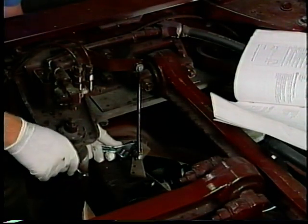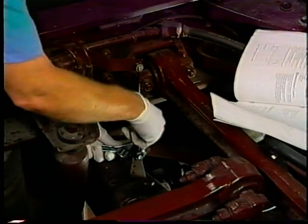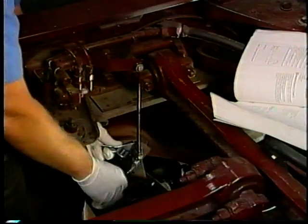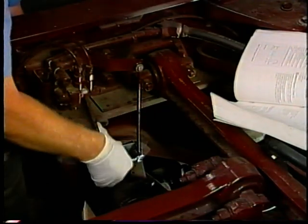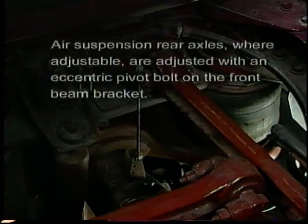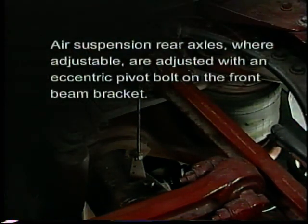Height control valves must be adjusted with the vehicle unladen, the air springs deflated, and the frame supported on suitable jack stands, or following the recommended manufacturer's procedures. Air suspension rear axles, where adjustable, are adjusted with an eccentric pivot bolt on the front beam bracket.